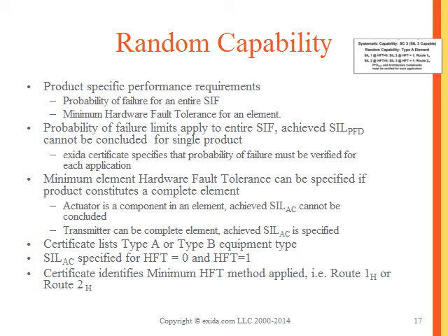If you have a certain level of confidence, and from the top of my head that's a 90% confidence interval on that data, then instead of calculating the safe failure fraction and looking at the tables for Type A and Type B, you use a table that is similar to the IEC 61511 table, where for field equipment there's SIL 1 with no redundancy, SIL 2 with 1 level of redundancy, SIL 3 with 2 levels of redundancy.